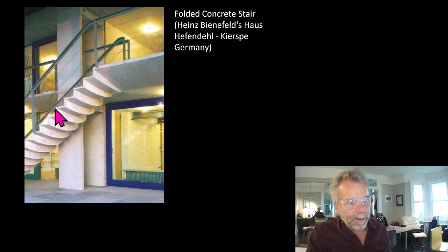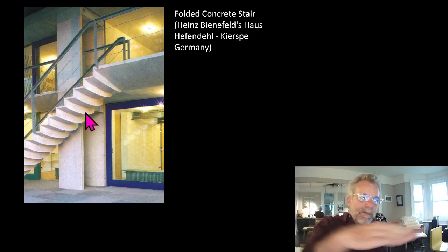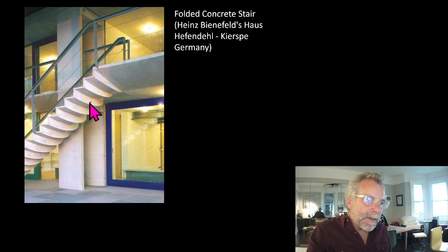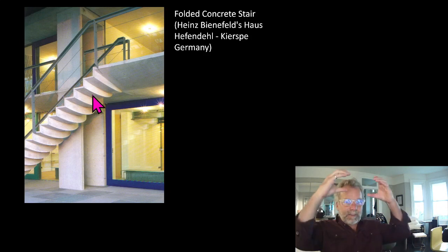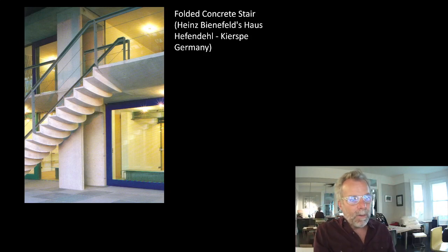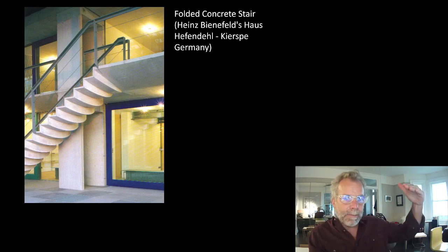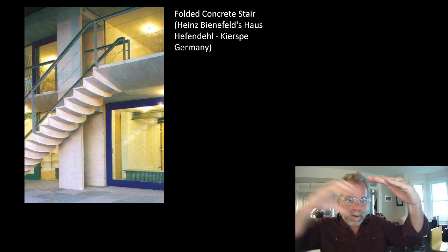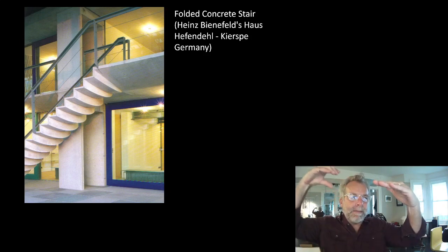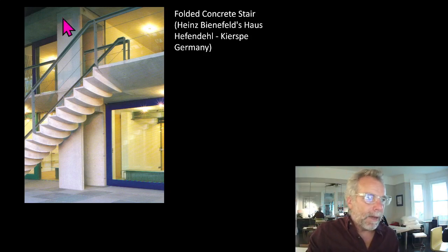So here's another trick. We've got this very thin edge here, which of course is inadequate to span the length of this. But by curving the bottom in the middle, we wind up with a net section that's a straight run. So within the volume of that stair, because it's straight on top and curved in the bottom, we have a strong enough beam running down the middle to span from end to end, while still giving us that really thin profile on the edge.